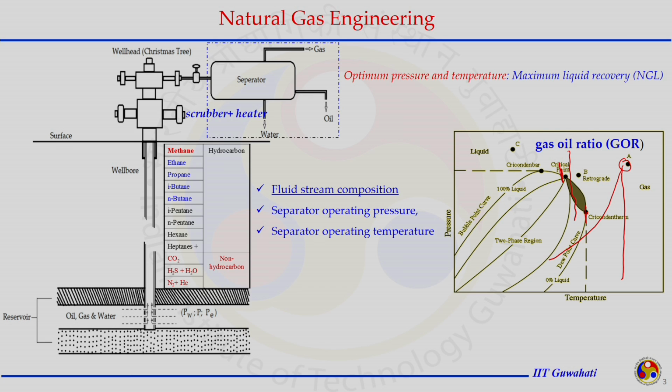Sometimes the storage facilities or other surface facilities available should also be adequate enough to store those compounds, so they do not go through revaporization again and lose the valuable hydrocarbon compounds in the form of vapor out of this production and processing system.